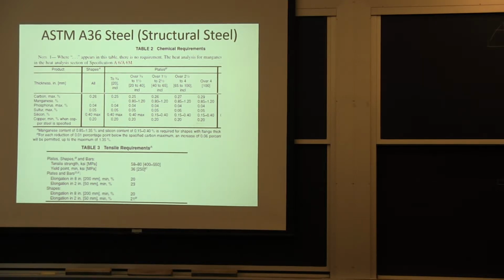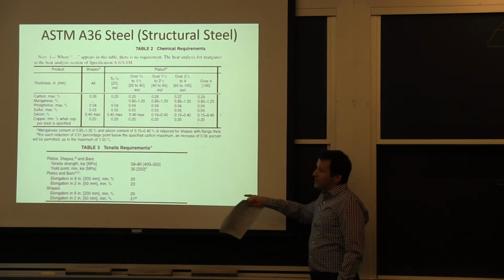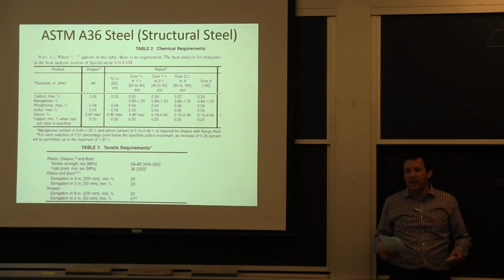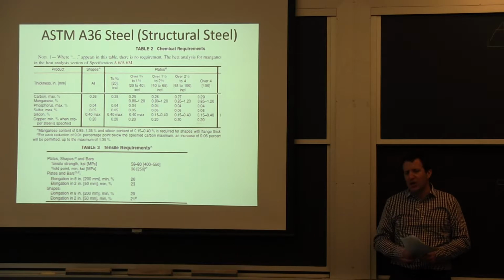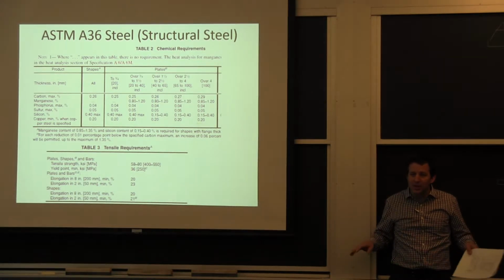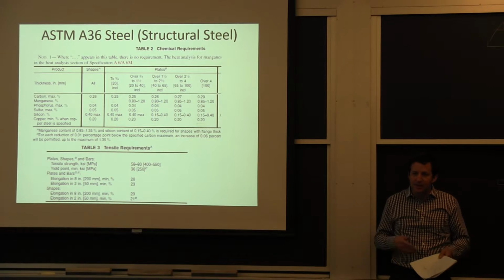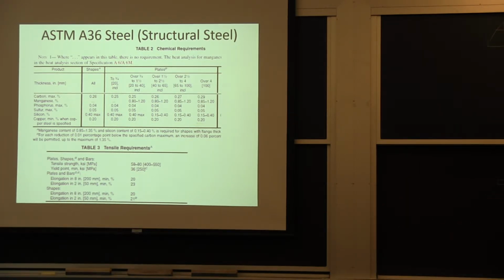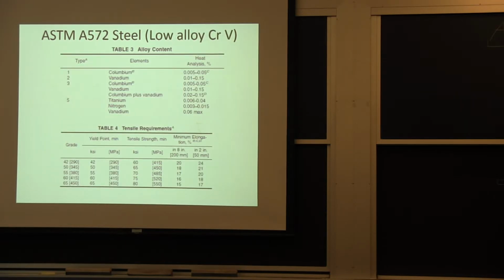Now, you can use it, but the properties you get out of welding this steel are the lowest. And I never really tried to take a steel that I didn't have a mechanical sample to say, oh, no, this is not grade 36, this is grade 50. You know, I would need to have the data to boost it up. But to say, okay, we're going to take it as A36, if it has all the chemistry requirements, was something that I've done day in and day out.